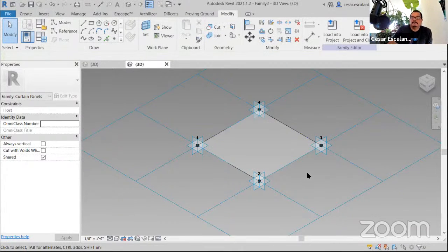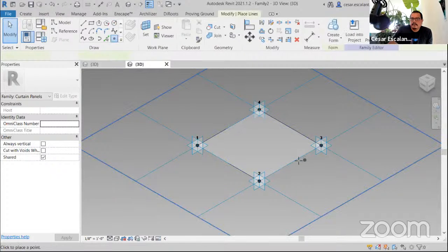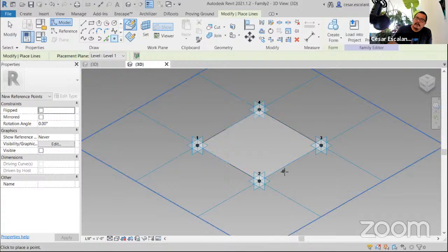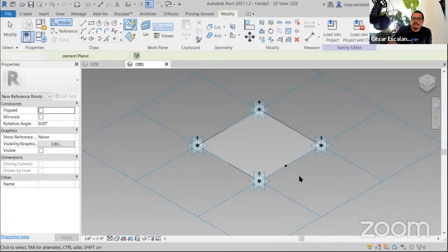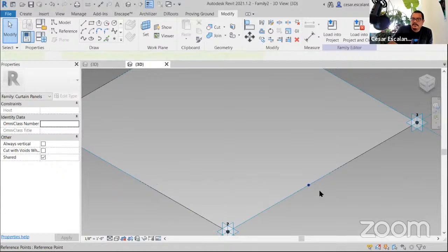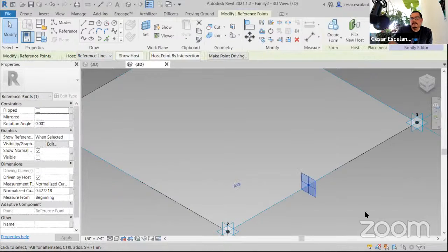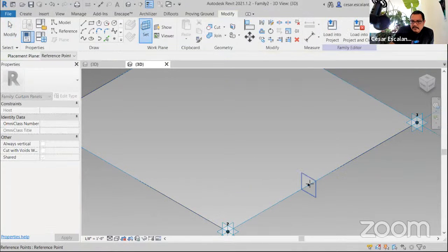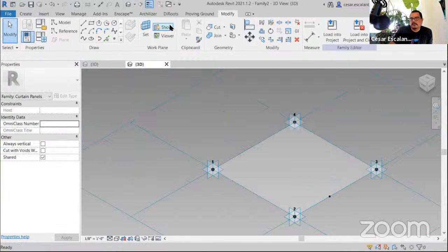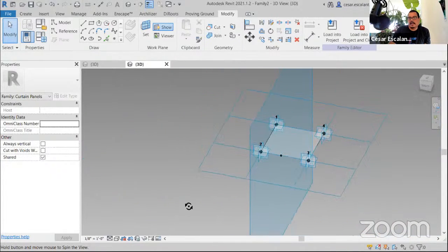And then I'm going to define a point in those edges of the surface, and use this point as a work plane to create like a frame around. I'm going to set the point as a working plane. This is a very important step. Working plane is everything in conceptual design. If you want to see this, just show it. And that is the working plane at that point.